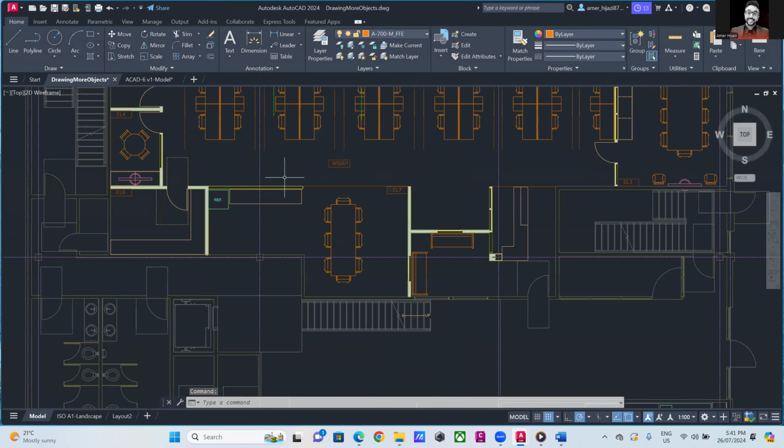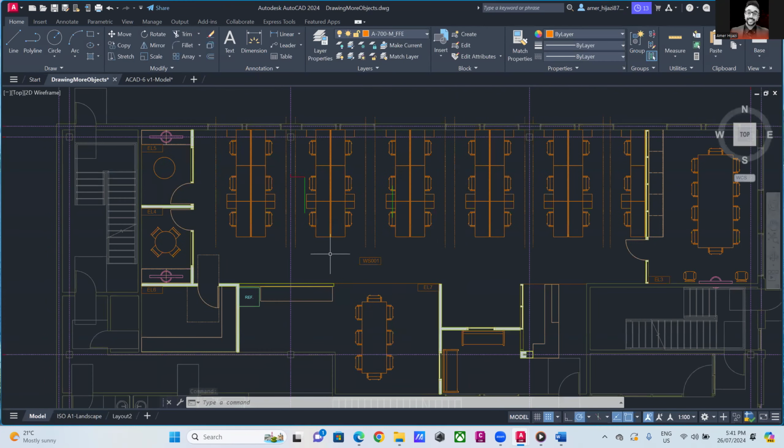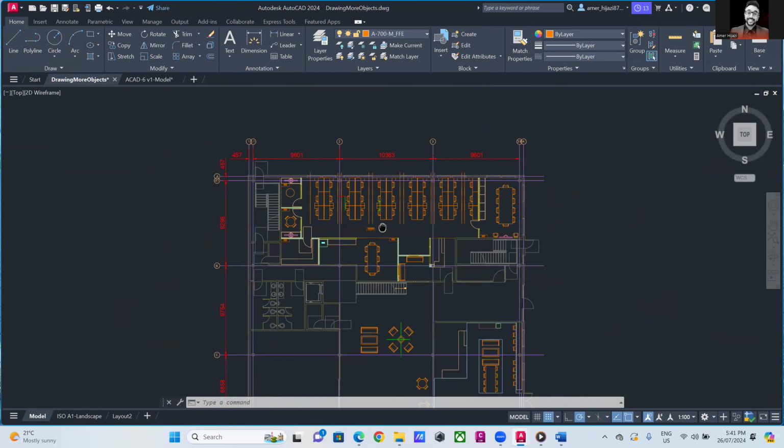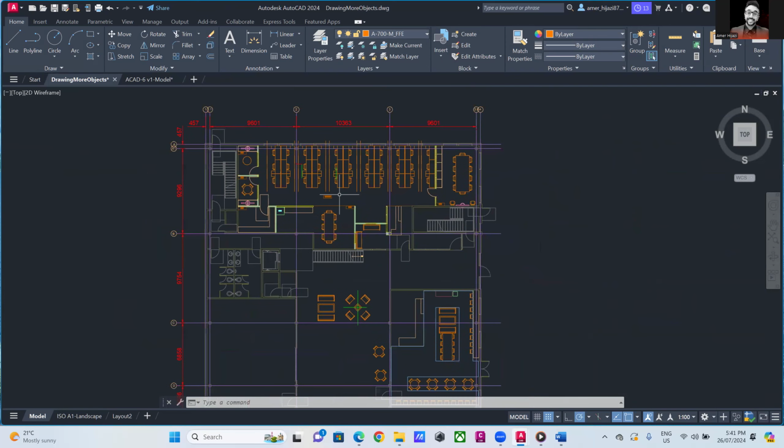When it comes to Autodesk AutoCAD, you are dealing with layers and 2D drawings. We'll see in a minute how you can even start reading the elevations from the Z perspective. But firstly, as you can tell here, you have several options. The Home tab is the main one, where we usually draw a line, circle, polyline, arc, rectangle, whatever. Also in Modify, we sometimes use copy, move, and rotate.